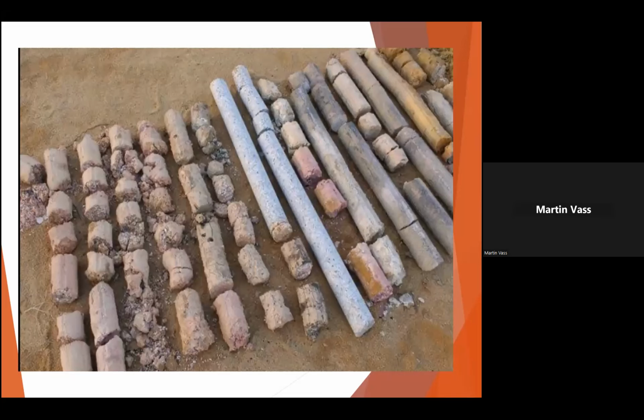So one has to be very careful when you reach hard material to say, oh, that's good enough. You've got to go quite deep to understand what your underlying material in fact comprises of. And certainly in places like Durban, etc., which has very variable soils, you may go fairly deep to establish your foundation conditions. Once you've established your foundation condition, this geotechnical report is given to the engineers and clients. You then go ahead with your design of your foundations.